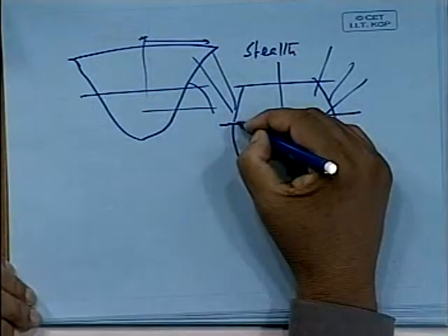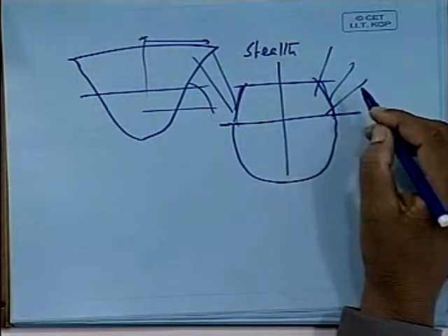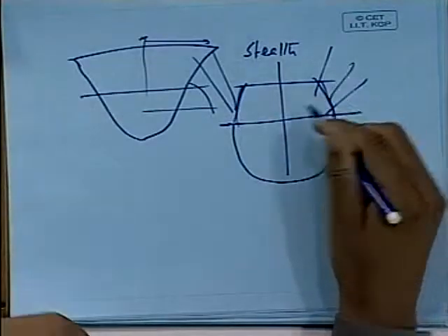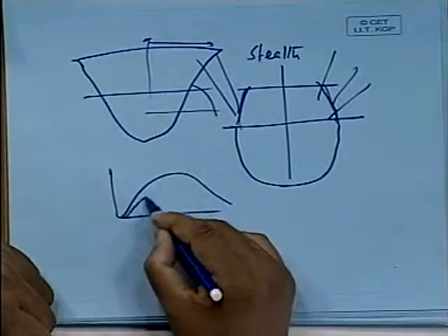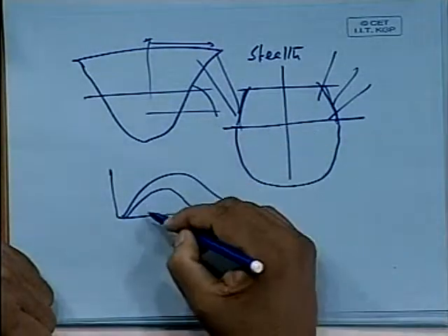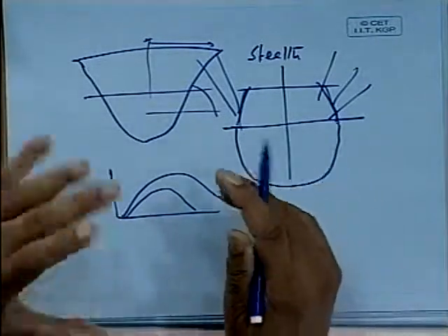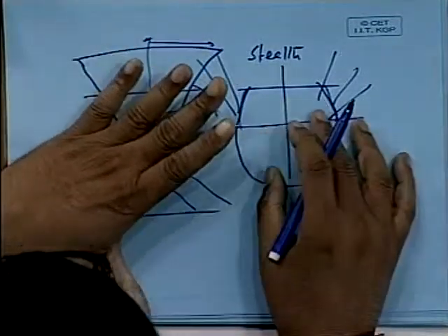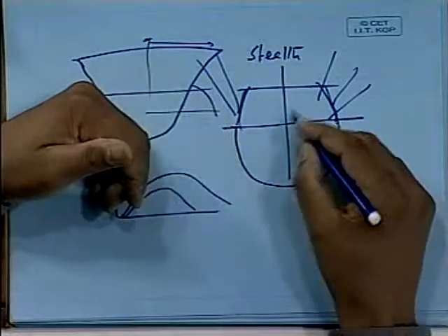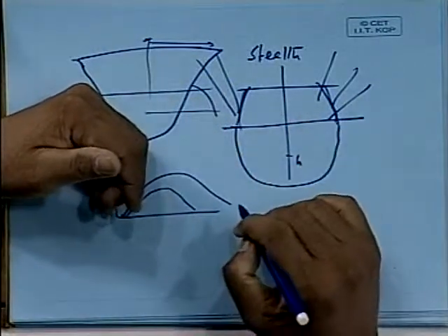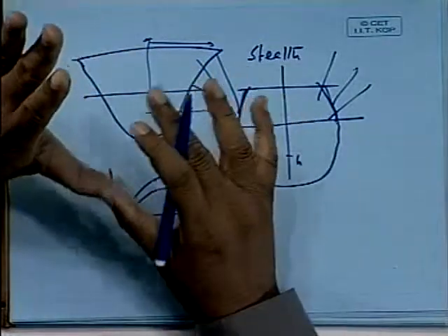So upward is better, like a tumble home, but it was never done before, because it always gives less stability. If you do that, your GZ curve will come down by a lot. Obviously, this is why most ships typically did not have that. But the Navy is now exploring this, because they are putting G sufficiently down. If you look at naval ships, they are stable up to a larger range. They actually have much lower G. So earlier, because of stability, that was not there, but nowadays they are exploring it.